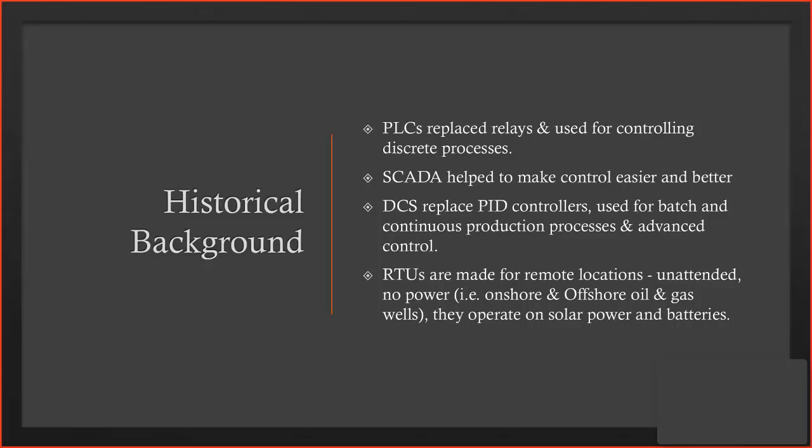So your process was centralized in one programmable logic controller, monitored by a SCADA. So I mentioned three issues. One, the connectivity and communication issue of different products. The second issue was support, and the third issue was that when my PLC is down, my whole process is down, not just a part of my process. It might cost me money, time, and many other things.